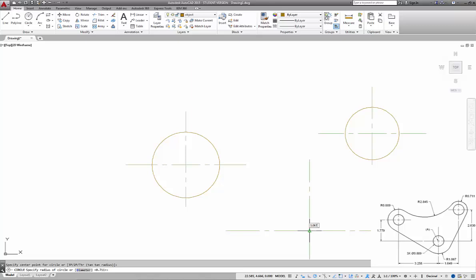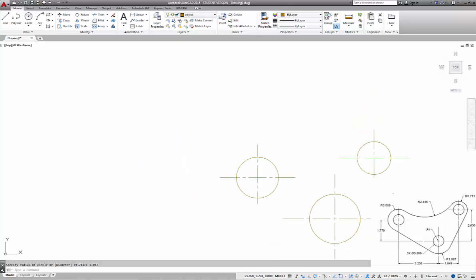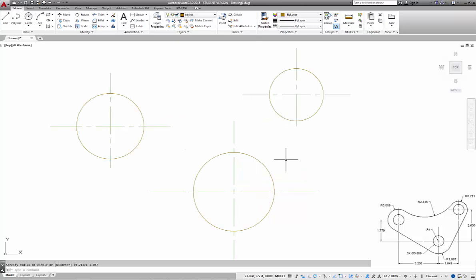It looks like a small arc, but it's easier to create it as a circle. And the reason being is because we're going to be working with tangents here. And having tangents working with us, it's so much easier to have a whole circle because you don't have to guarantee that exact location initially.